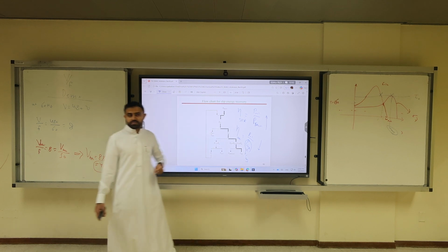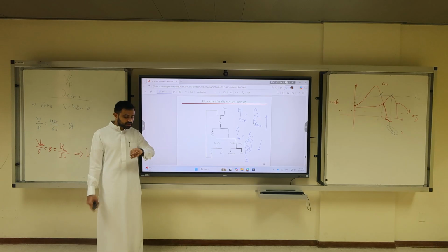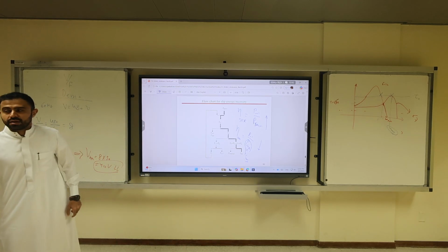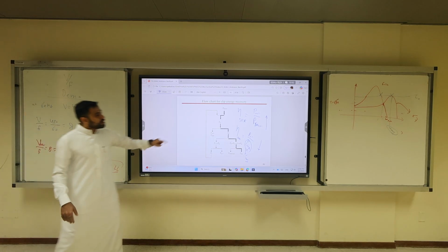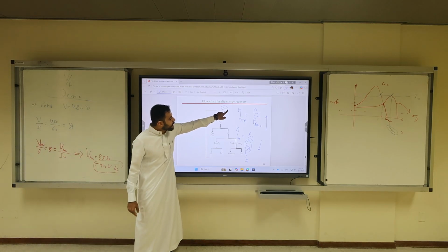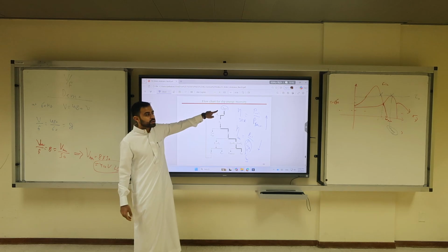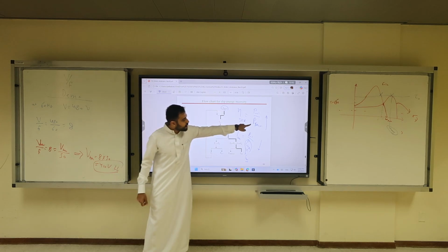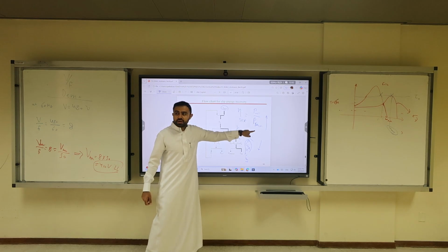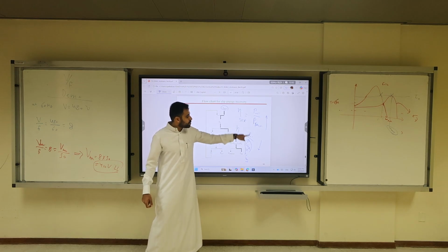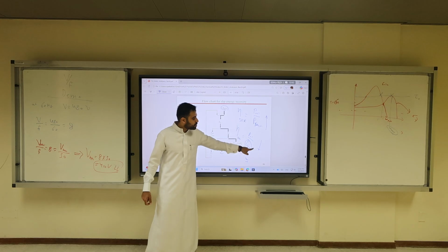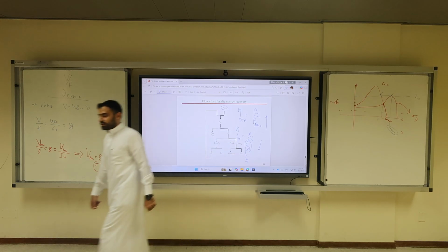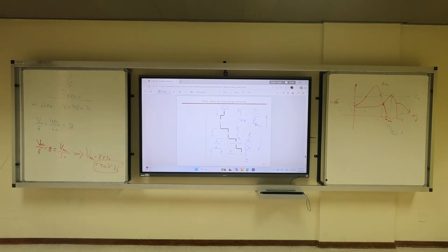Think about it a bit. This is a nice trick. We will start with this trick, remind us next lecture. Okay? In summary, the trick here is you minimize your source supply because you're recovering some of the energy. If you minimize the source, you increase the efficiency. If you make the source more, your efficiency is lower. So slip energy recovery would improve the efficiency. Thank you all. Any question?